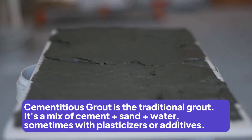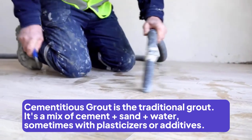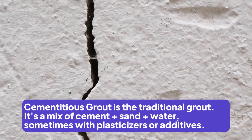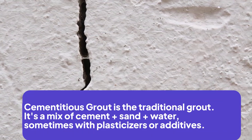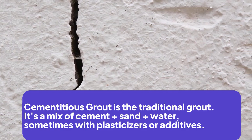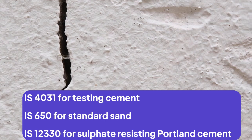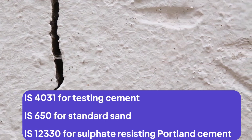Now where can you use it? It is used in tile joints, general void filling, or repair in dry or mildly wet areas. It is affordable, easy to use, available everywhere, and budget friendly. That is why it is the number one choice for grout. As for the IS code preference, it is IS 4031 for testing of cement, IS 650 for standard sand, IS 12330 for sulfate resistant Portland cement, and IS 456.